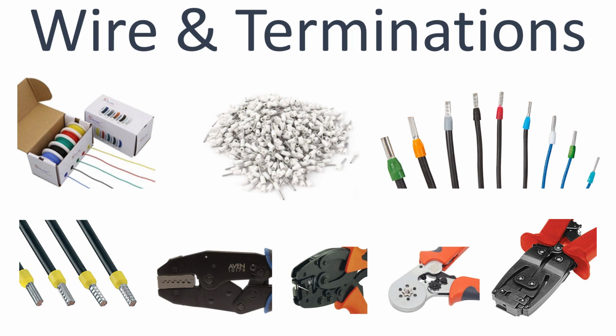Now the switches, those toggle switches and the push buttons and lights, you're going to have to solder wires to those. But the wires that come out of your digital field device simulator and go to your controller, that's where you use the ferrules. Ferrules come in different sizes and colors. I always use 22 gauge wire, so I buy ferrules for 22 gauge wire. The crimpers, though, that's another story.